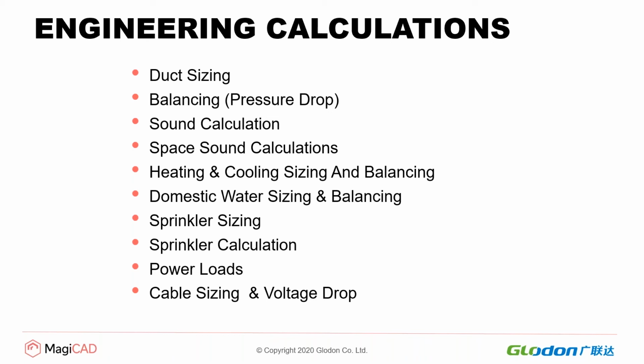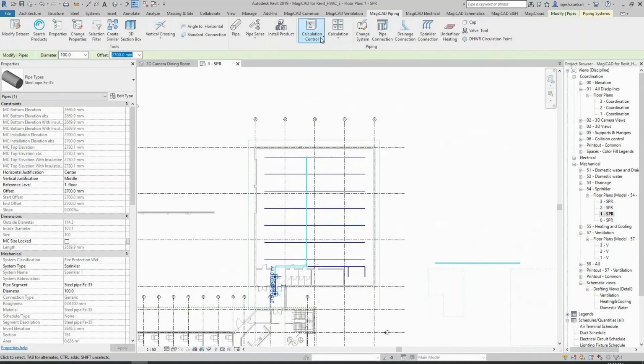And not only sprinkler calculation, we can also do the electrical calculation. For the electrical calculation, we collaborated with Schneider Electric, and we are using the Schneider Electric calculation engine and the IEC standards. So we can do the power loads, cable sizing, voltage drop, and the short circuit calculations in the electrical. So here we're going to see how we do the sprinkler calculations.